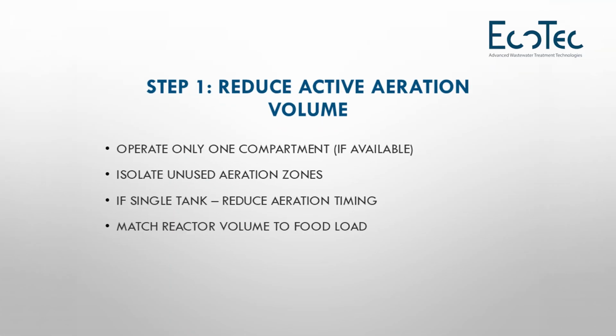In a partially loaded reactor, we have assumed 50% volume. Let me also make a few more assumptions. Let's assume the plant has two reactors or two compartments in reactors. We can operate only one reactor. If there is a single reactor, we can reduce the aeration duration. If the entire tank runs continuously at low load, you are overstabilizing biomass. Design without flexibility is not process design. It is infrastructure without intelligence.